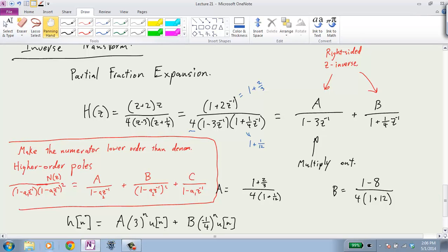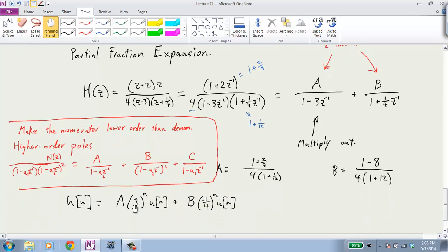Yeah, so that's one thing you could do. You say, well, here's a product, like you're saying. So do an inverse on them separately and then do convolution. I think it'll be more work because the partial fraction expansion isn't too bad. It depends because they're u's, you're right that they're u's, but they're u's times an exponential. This isn't a constant here, right? This is a growing function. So doing this convolution would probably take more work.